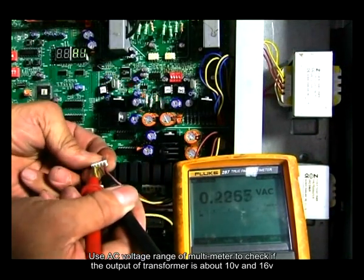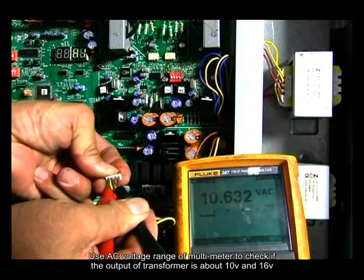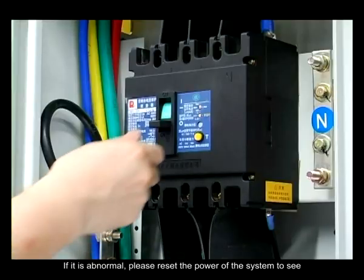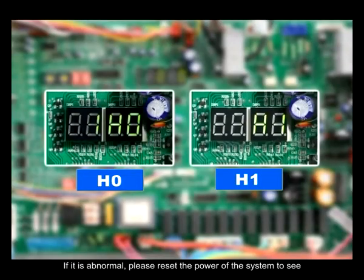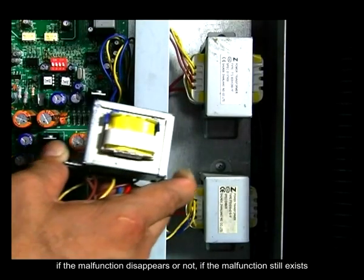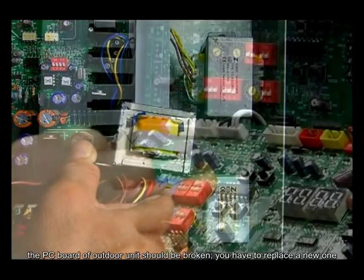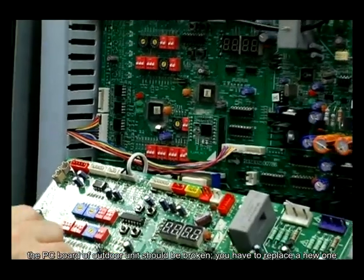Use the AC voltage range of the multimeter to check if the output of the transformer is about 10 volts and 16 volts. If it is abnormal, please reset the power of the system to see if the malfunction disappears or not. If the malfunction still exists, the PC board of the outdoor unit should be broken. You have to replace a new one.